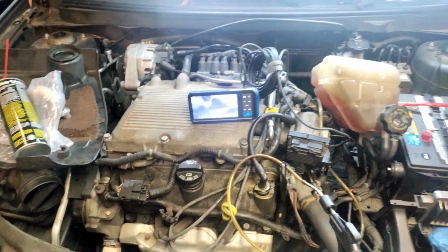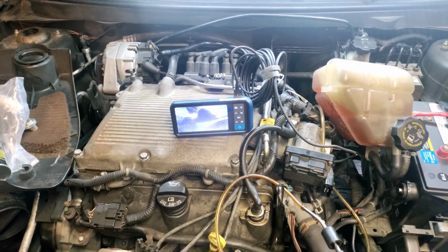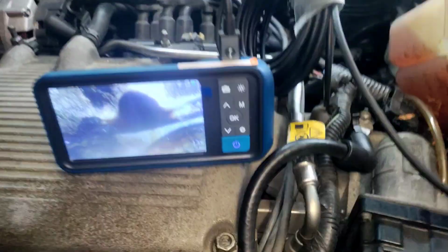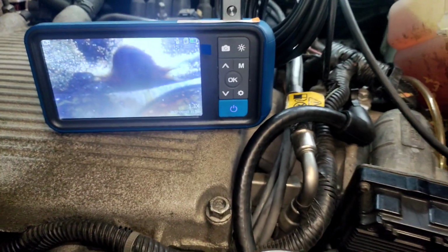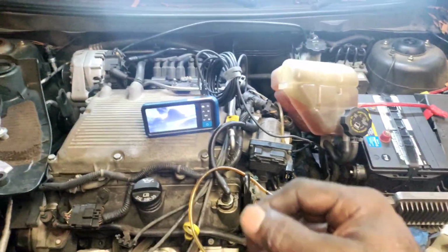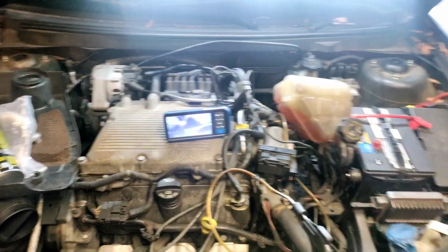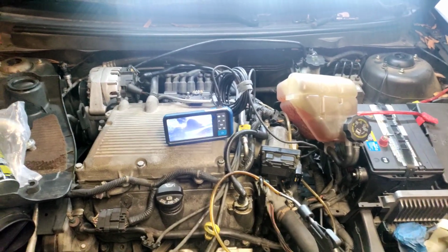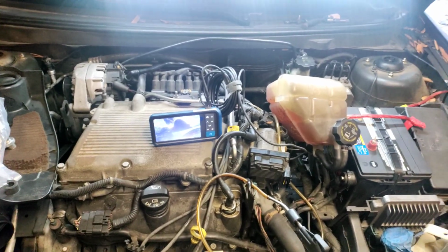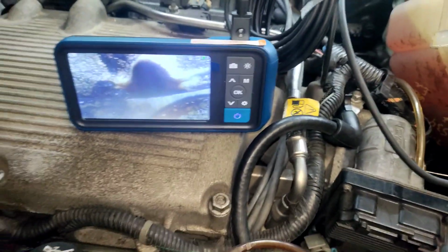So it's probably a really small obstruction. I'll probably let that soak and just keep picking it and blowing through there, and it'll eventually free up. But I want to get it 100% unclogged if I can, but I don't think I'll be able to get 100%. What I normally would do is put in a brake cable, like an old throttle cable that the vehicles in my generation had, just the inside of it, put it on a drill, and it'll work perfectly. But I don't know where in the world I put it.